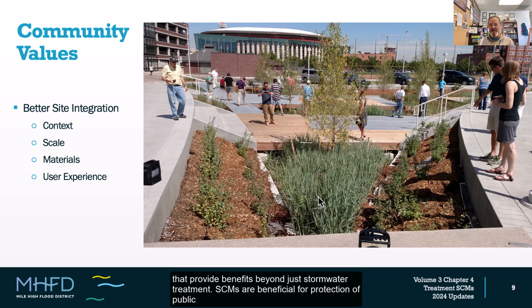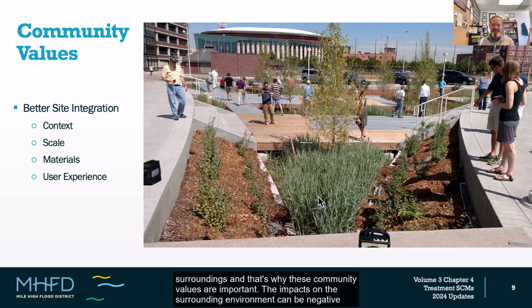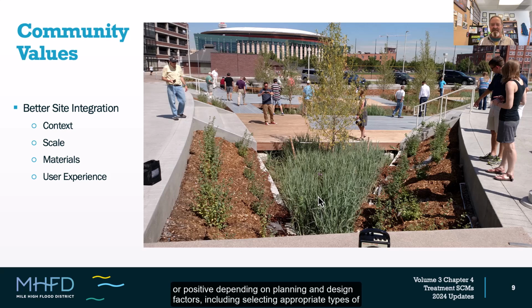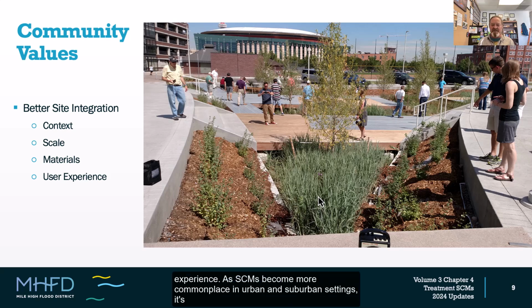SCMs are beneficial for protection of public health, safety, and welfare, and are also required by local governments that are MS4 permittees. However, these types of facilities can also have significant visual and experiential impacts on their surroundings, and that's why these community values are important. The impacts on the surrounding environment can be negative or positive depending on planning and design factors, including selecting the appropriate types of SCMs for the site, proper siting of features, design details, materials, and finishes of major elements, grading and landforms, vegetation, scale, and the overall user experience.